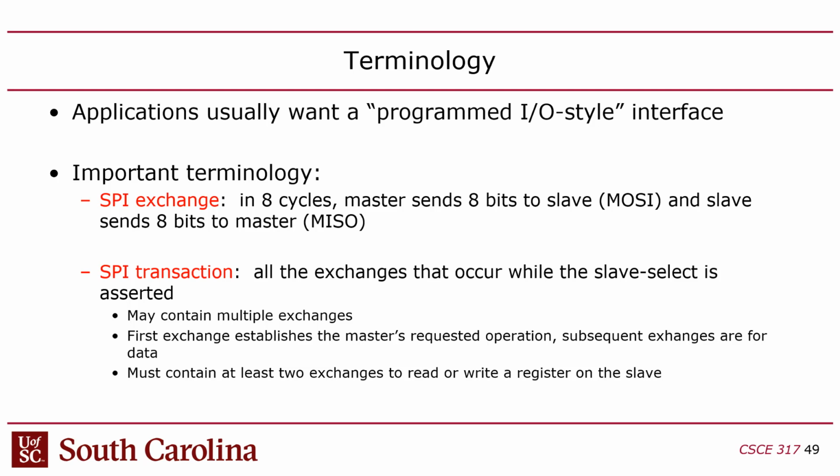Okay, so there are two terms here. There's an exchange, which is every 8 bits. So every 8 cycles of communication on an SPI is an exchange. But a transaction is when you do multiple exchanges to do a load or store operation, right?